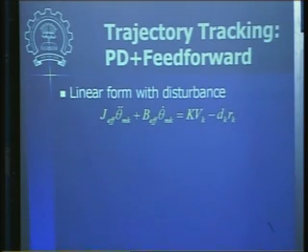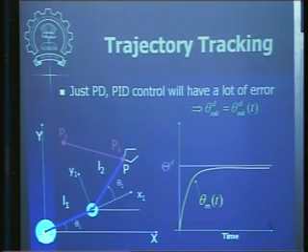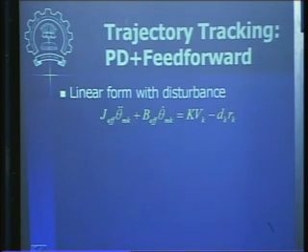Because we are talking about a tracking problem now. So that kind of a control algorithm will not work here for the trajectory tracking kind of a problem. So what is a solution? We see why this is not catching up, because the disturbing terms, this inertia and the damping terms, are not in some sense fed forward in the control law, which is this.